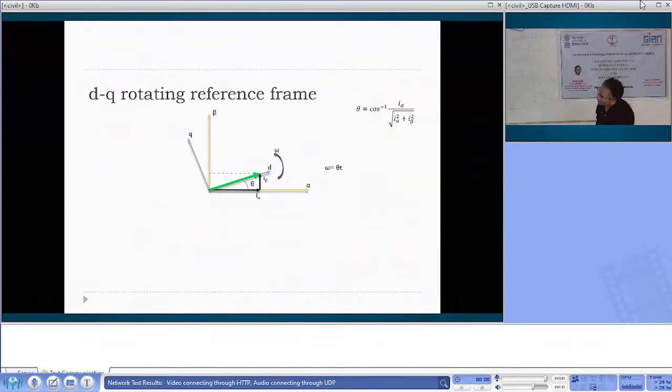So you have to orient your voltage at this D axis, as if you are sitting on the D axis and the D axis is rotating. If you are sitting on the moving object, it appears to be stable. That is the theory behind this. So when you are sitting on this D axis, the variables look stable, stationary, or a DC value, not a time varying value.